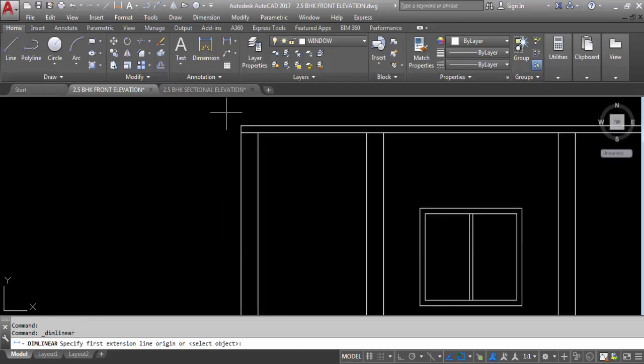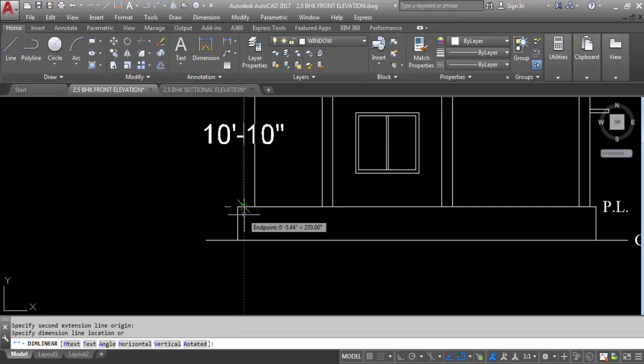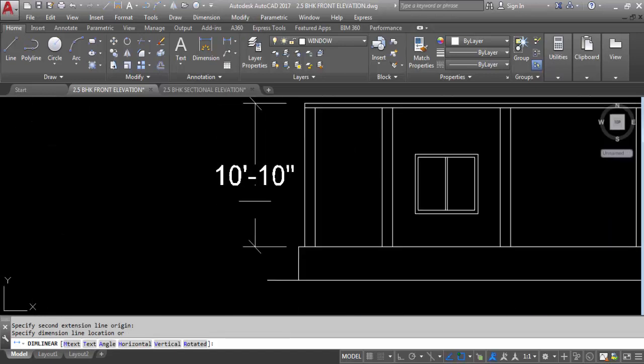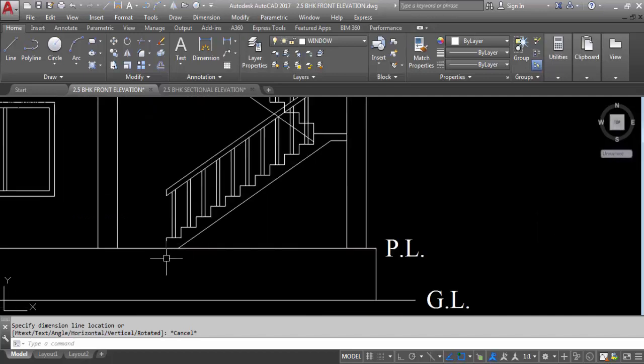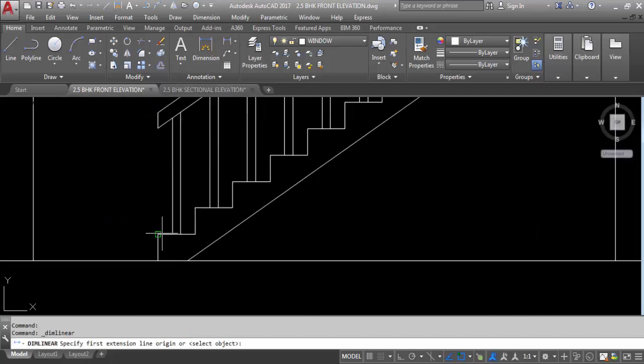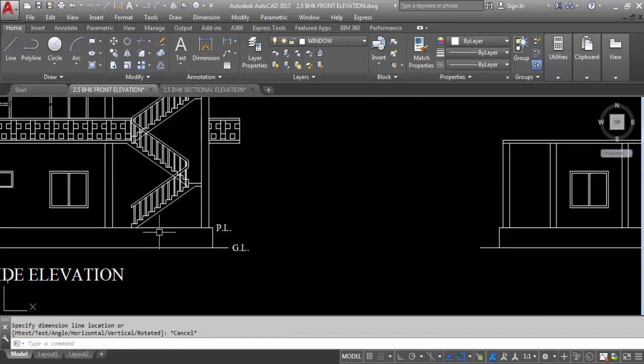So here height of roof slab from plinth 10 feet and 6 inch. So riser height is 6 inch. So 10 feet 6 inch is divided by 6 inch means 22 numbers of riser we have. So tread 22 minus 1, 21 numbers of tread. So riser you can say 6 inch and tread 9 inch. So rise 22 numbers, tread 21 numbers.